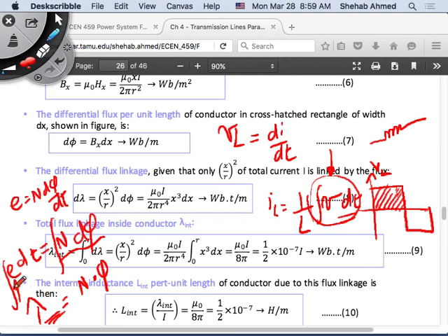So what is this flux linkage? It is the integration of the voltage across each of these turns. I have an inductor here with a certain number of turns, and I've placed a certain voltage across it. This voltage has to have an average value of 0. Remember, it's like a capacitor: you cannot keep charging a capacitor. You will charge a capacitor, then discharge a capacitor.